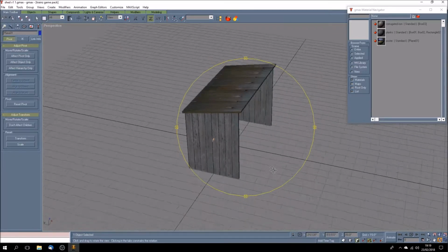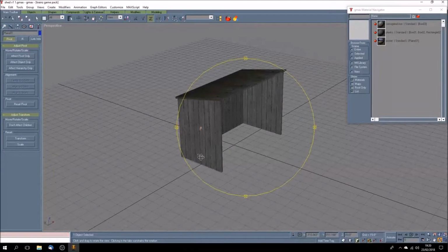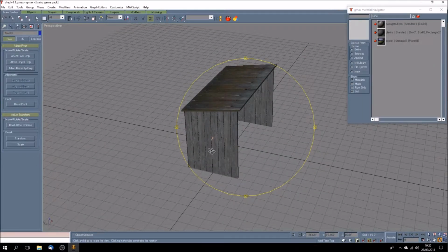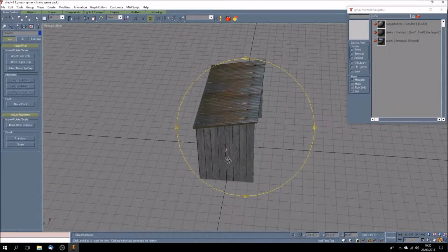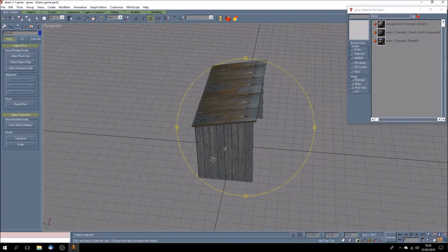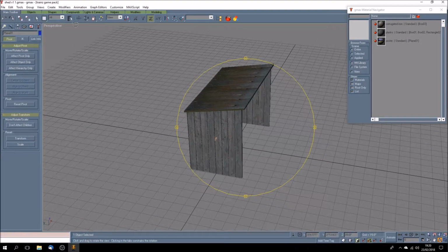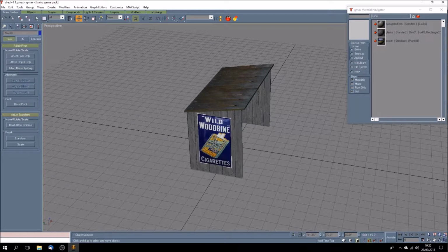But of course, because our shed wall is 2 inches thick and the plane has no depth in it whatsoever, it has disappeared. It's buried in the wall. So we need to bring it out from the wall. So let's select and move X. With this hovering over, I think I can just bring it out. Here we are, and there it is.